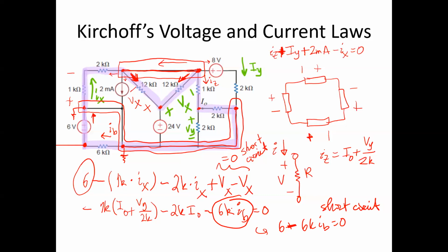So essentially the voltages for the only elements for which we need to sum the voltage are the 1K, the 2K, the 1K here on the right hand side, the 2K here on the right hand side, and we're done. So it was really just a sum of four elements and their currents to do the problem. Okay, so this is again a case where you have to make observations to make the problem easier for yourself than what it otherwise would have been.